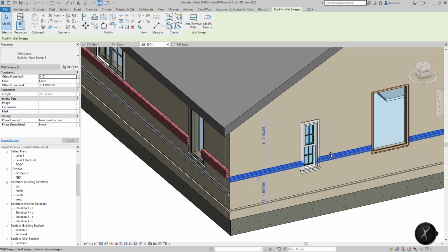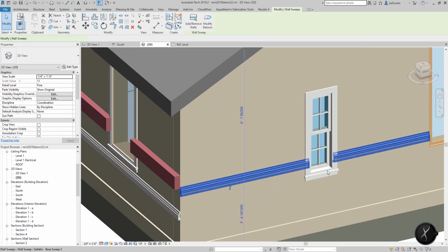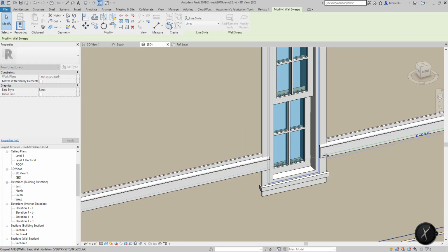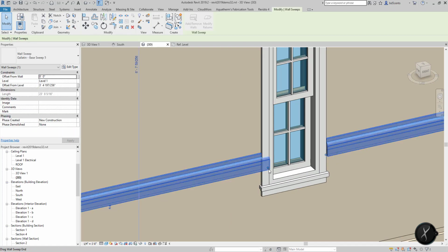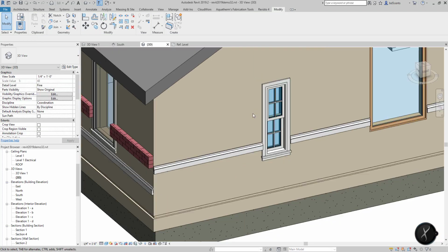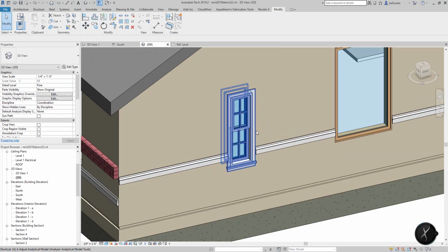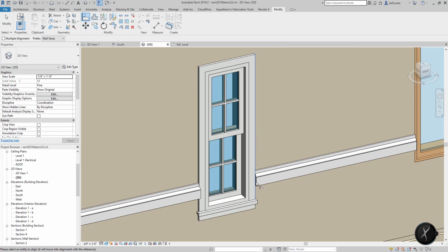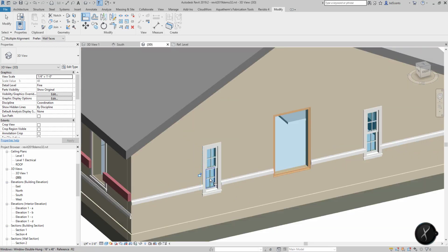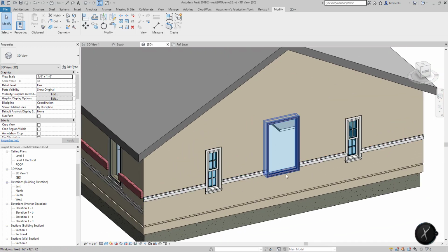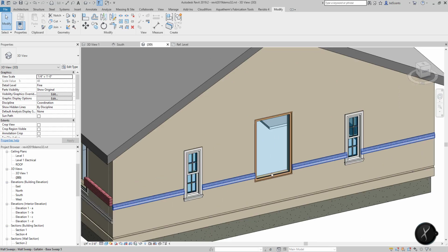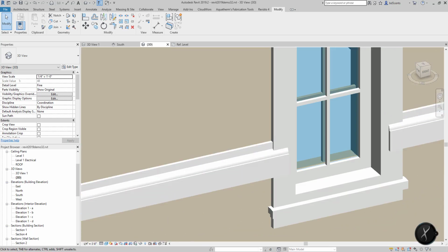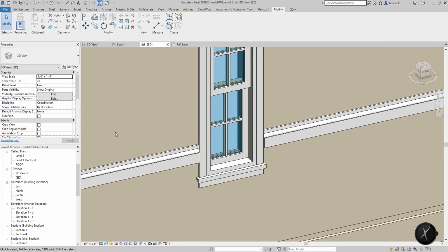What we could do is move this up and it automatically splits it. Then from there I can adjust that value to go back if I want it to be further back rather than in the trim of that window. So there are a lot of really beneficial things. Now I can align and tab to that face and that face to ensure that they're actually aligned correctly. Did you notice how that moved? That's super valuable. If you're cutting through windows or walls, that helps do it a lot better, to where it's not going to overlap like this is, but will actually cut correctly as this is.